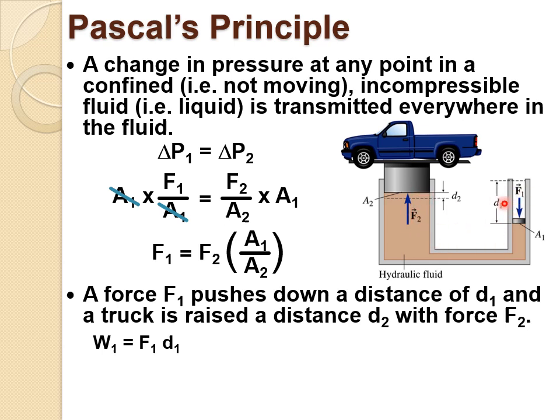So essentially this is a conservation of energy. The work done over here is equal to the work done over there. Let's say this force F1 pushes down a distance of d1 and the truck raises up d2 with a force of F2. The work I do on this side is going to be equal to force 2 times area 1 over area 2 times distance 1. Now you can see that area 1 and distance 1, the cross-sectional area and the distance it moves down, is going to be a volume, and that volume transfers over.